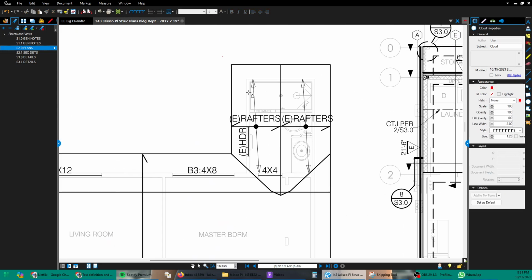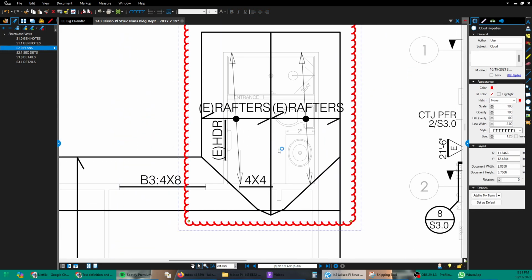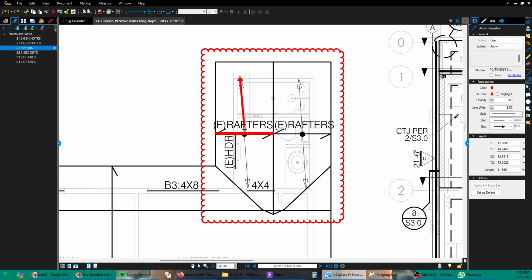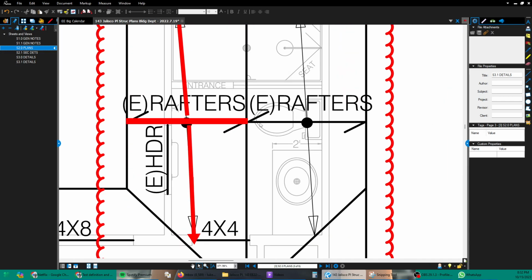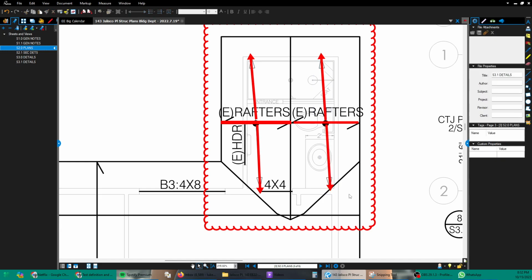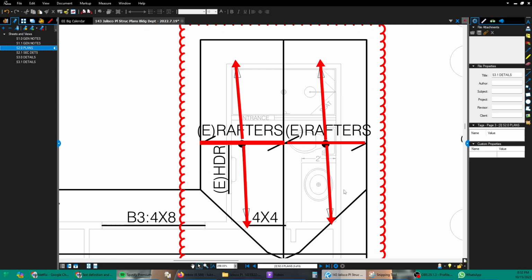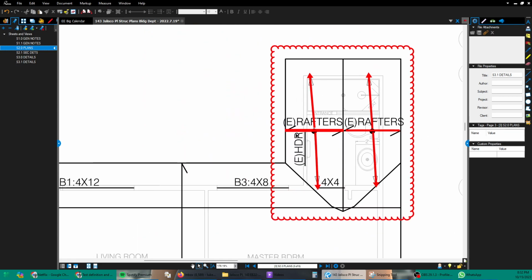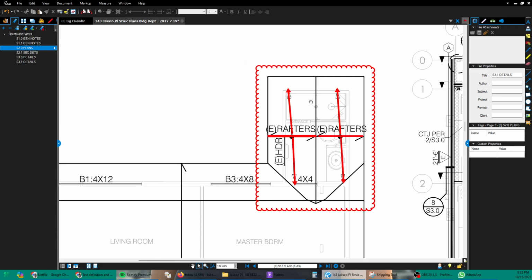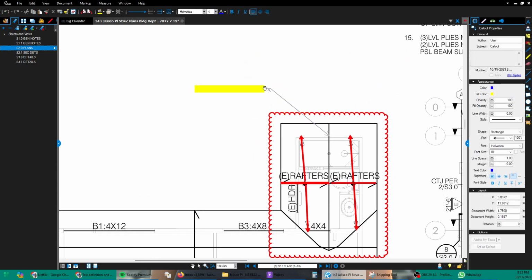In this small area, we have other framing. In this case, it's rafters running this way, and they exist over an extent defined by this region, by these arrows, right? And then we have more rafters here at 2 feet on center. Almost always the roof framing is spaced 2 feet apart, and these arrows indicate the extent over which those rafters exist. Notice that the rafters here are traveling perpendicular to the ridge. This is the ridge, roof ridge.